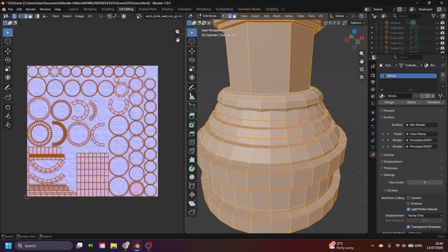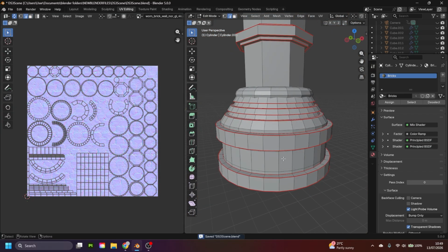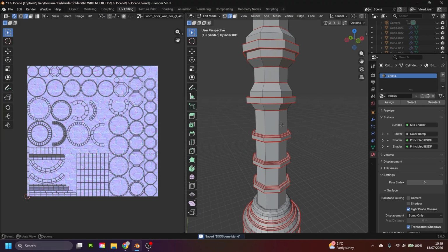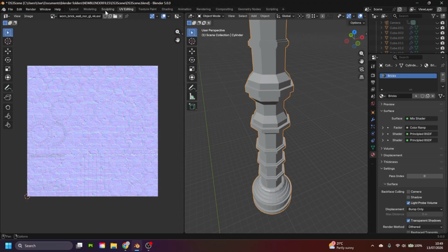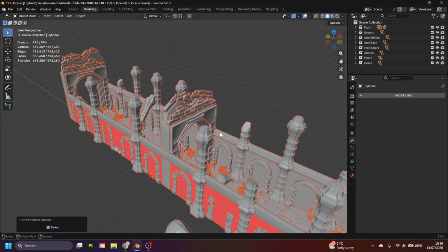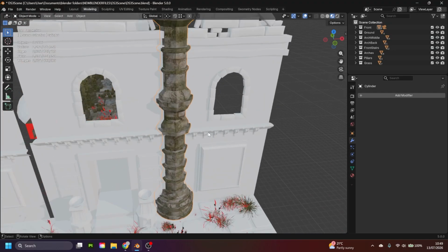If I shade smooth, it's going to look a bit weird now. So I need to add my bevels, which is basically just selecting all those points where I just UV unwrapped it and adding a slight bevel, 2 segments, a small one. And I can do that later. That's quite an easy thing to do. Just bring everything else back. For now, I think this looks okay.